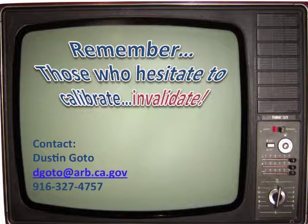On your multi-point calibrations, say for instance, theoretically, you have an instrument that can go 0 to 1,000. What if you know for a fact that most of your data, or let's say all your data, is 0 to 100? Would that influence the points that you choose for your multi-point? Yeah, typically, you still want to run at least at 80% of full scale.